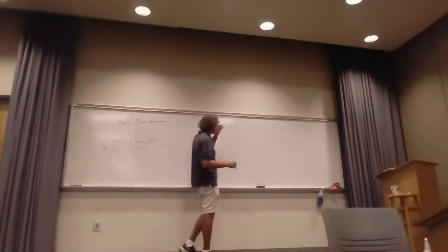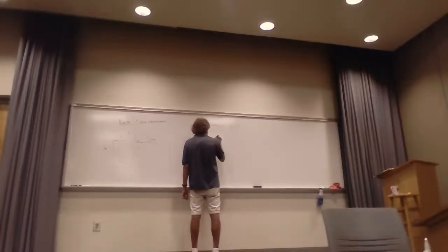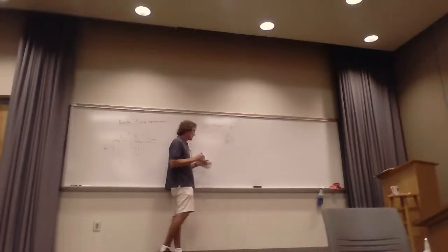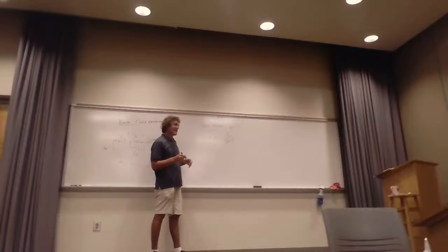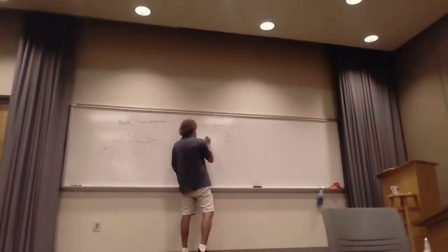Now, I can go ahead and simplify this a little. So it's equal to sL plus, I'm just going to leave it as L here because there's only one inductor, plus, and then if I go ahead and divide by C, I get 1 over C, over s plus 1 over RC. And when I take a look at this, and I go ahead and plot it versus magnitude of the impedance, this is Z.